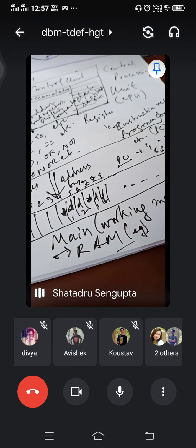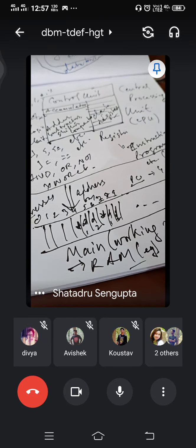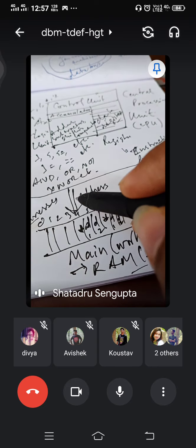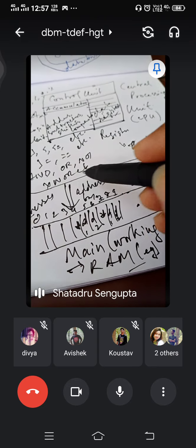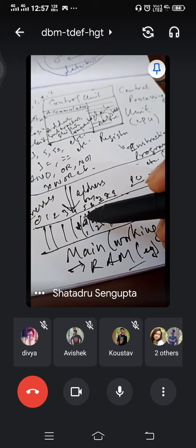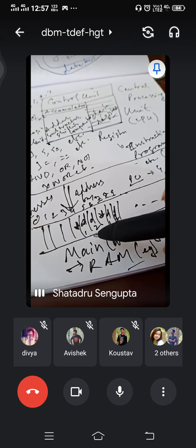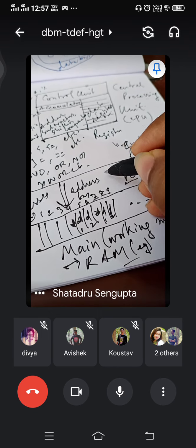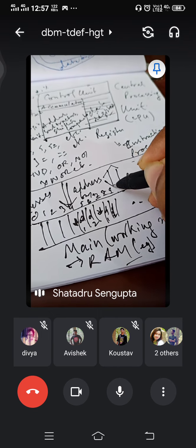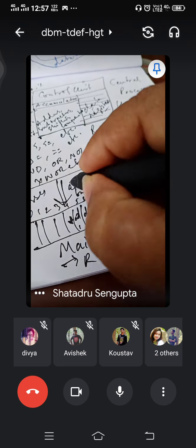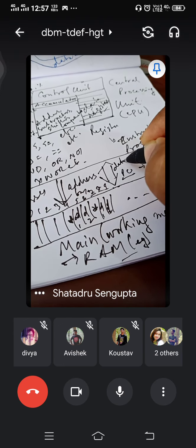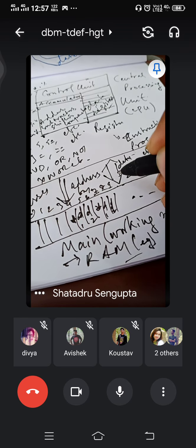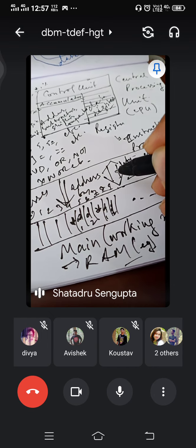Okay, and this program counter is adjusted accordingly, by incrementing it, so that the control unit will automatically consult the program counter, give out the address. The address will select the particular line through the address selection logic, and once that is selected, then data will flow into the computer, or it will flow out to the memory from the computer. So that is why it's a two-way bus.